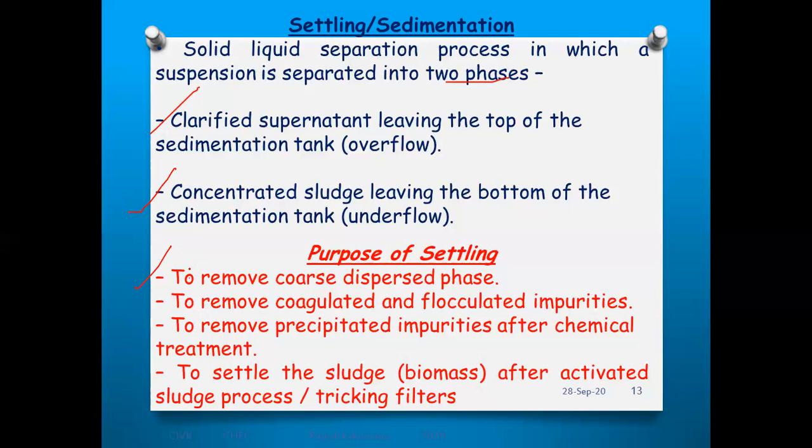Coarse means the hard phase, so we remove it. That's the first function or purpose of settling. The second one is to remove coagulated and flocculated impurities.